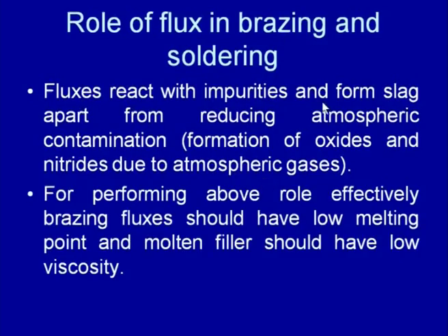These impurities can be formed by the reaction between the molten filler metal and the atmospheric gases, forming their oxides and nitrides. When these oxides and nitrides are formed, the fluxes react with them, and after reaction they form slag, and the slag is removed.